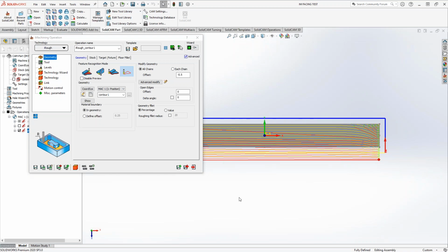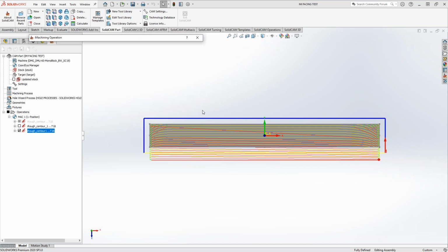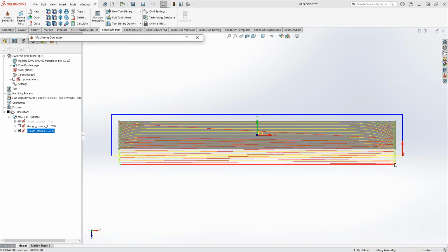Like that. Let's see if I can get that shading off, get this out of the way. And you can see now that it's still doing that outside contour, that outside entry, no longer helical entry because it still has an open edge, but it's going back and forth. And basically what this is, D-slot trochoidal in the corner, even though it's not really necessary. You can see it's doing D-slot trochoidal, and it's doing a really large separation channel. It's not really a separation channel because there's no islands, but it's doing that long, along the length of the part.